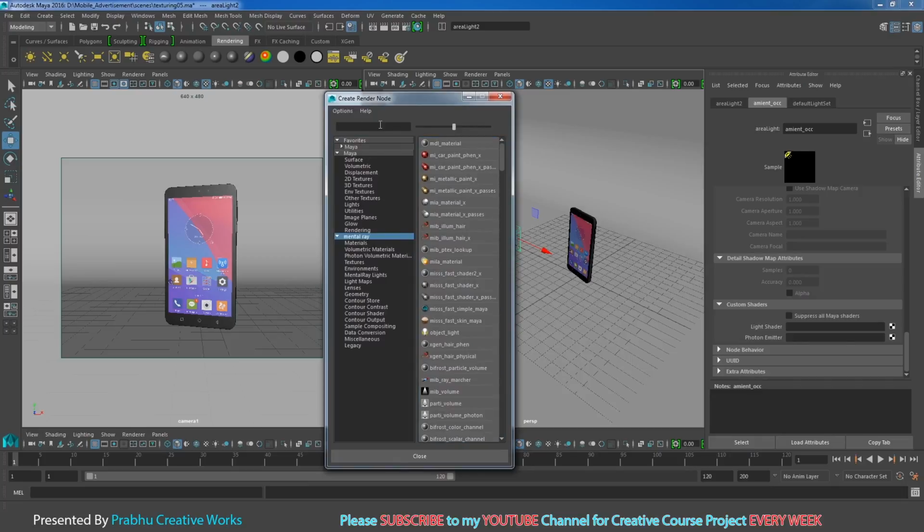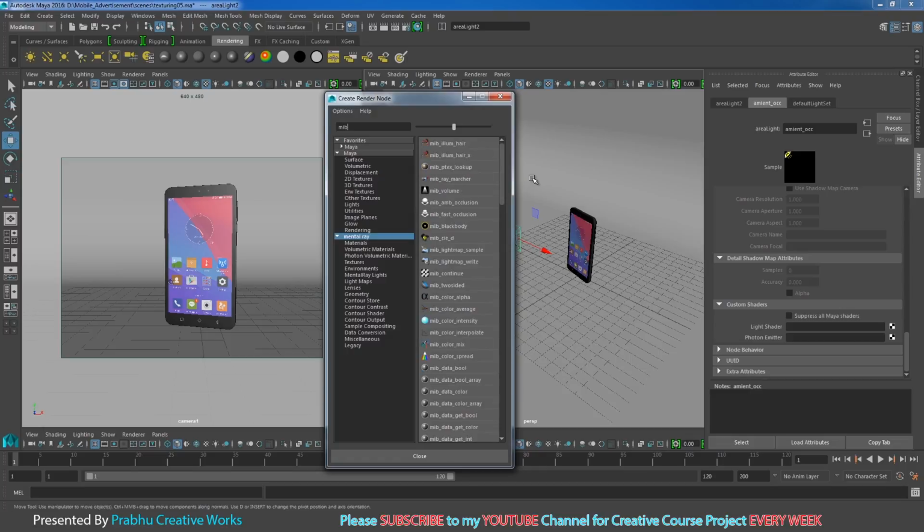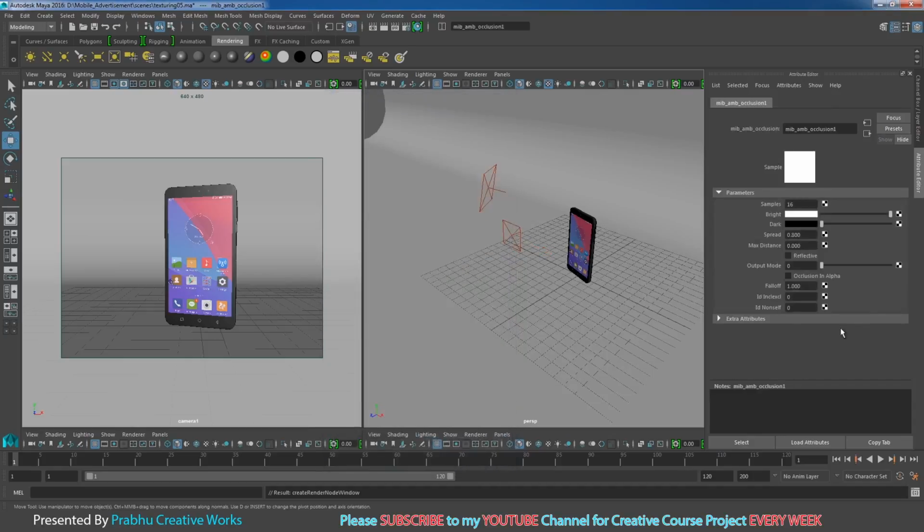Here you need to search MIA, so type MIA over here, and click on ambient occlusion, mia ambient occlusion. That means it will apply as your lens shader. Give samples as 64 and maximum distance as 5 like this.